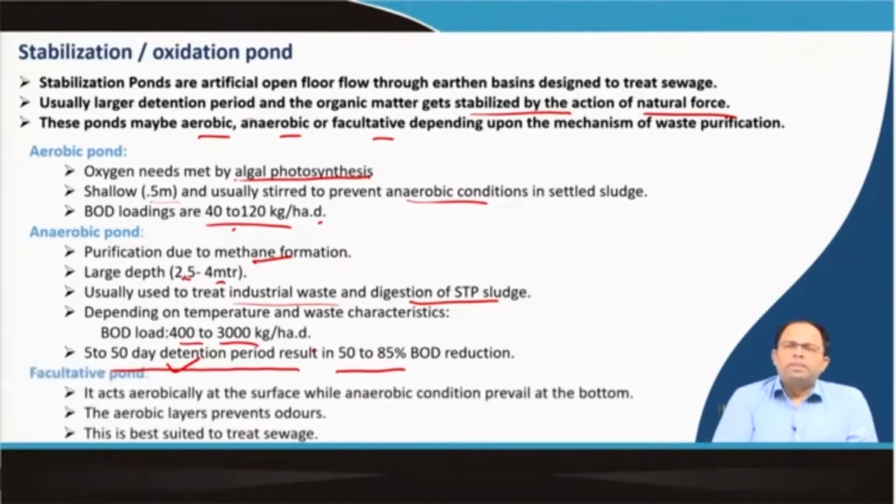So, the problem with an anaerobic pond is that there is bad odor, and methane formation takes place in the lower levels, whereas aerobic ponds do not have any kind of bad odor and these other issues. So, it is better to have a system where we can use both these processes, so that we can achieve the 85% BOD removal of anaerobic systems. That means, if we combine both the systems, the effectiveness of BOD removal will probably increase.